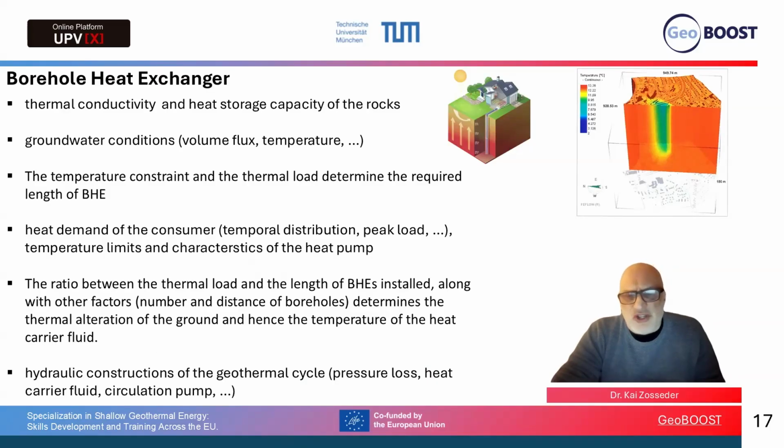Also, groundwater conditions should be considered, because groundwater is quite favorable for borehole heat exchanger installations. Groundwater carries the heat back to the borehole heat exchanger, so it's quite favorable to have good groundwater conditions.